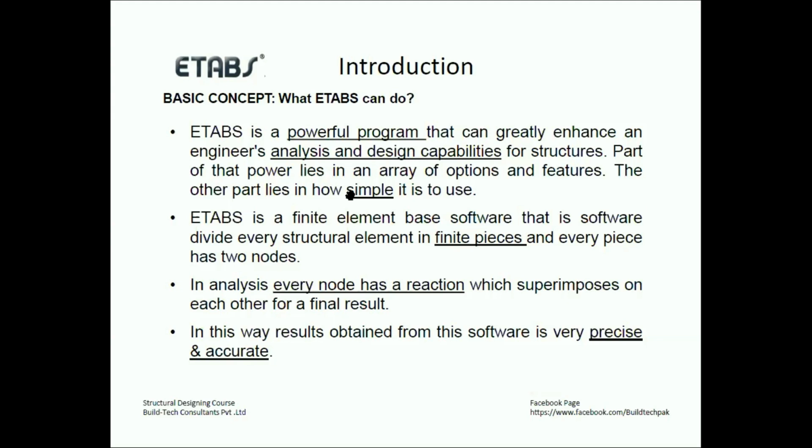The software is a precise one. It is capable of producing the reactions, the shear force diagrams, and the bending moment diagrams. You can apply loads on the structures and see the deflections, like serviceability states. Once the design is completed, you can even check how much steel is required in the sections. So this has precision and accuracy.